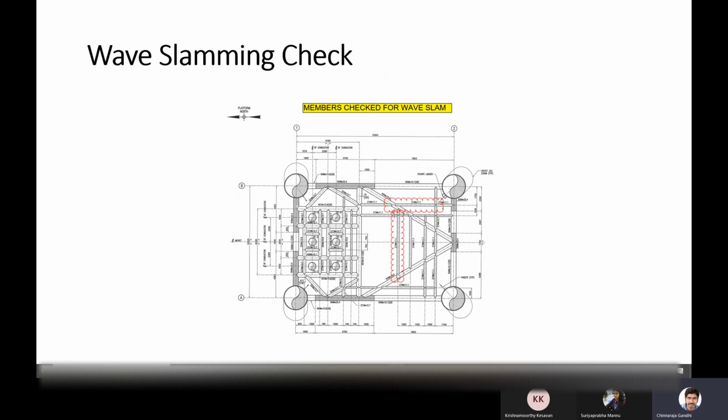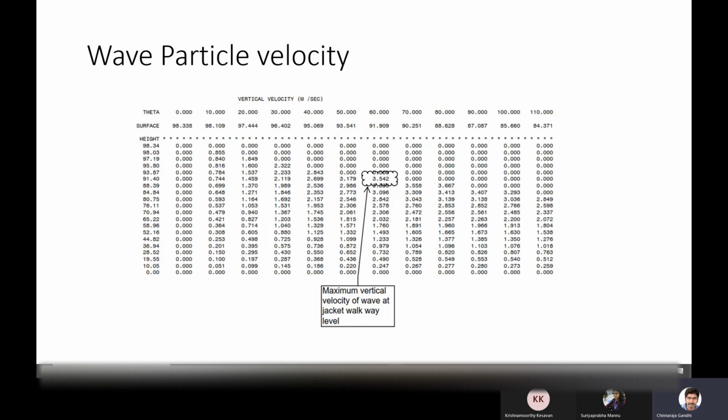This is a continuous beam. You know the bending moment is WL square by 12 or WL square by 8. You can select the bending moment formula, and then the shear force you can calculate from the given load. What is the shear force, and from the sectional property, you know the maximum allowable bending stress and the axial bending stress. From there you can calculate the UC.